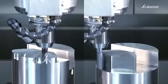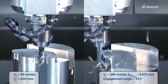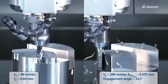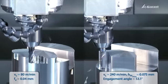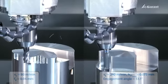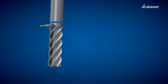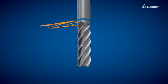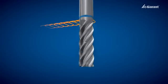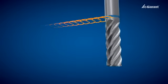The result of this strategy is that high cutting speeds are allowed at full cutting depth, whilst at the same time achieving significantly reduced tool wear. This procedure is achieved by overlaying two opposing movements: straight line and elliptical.